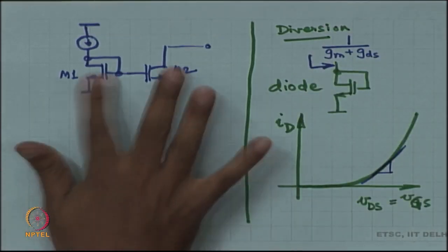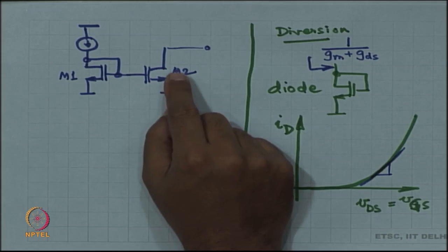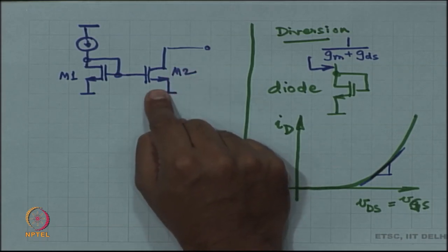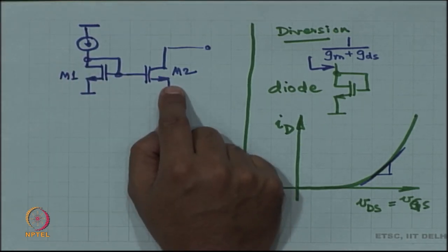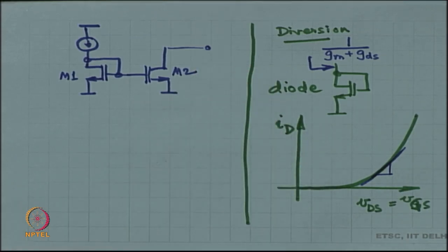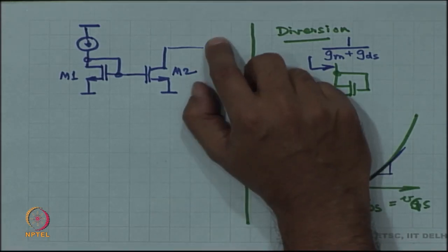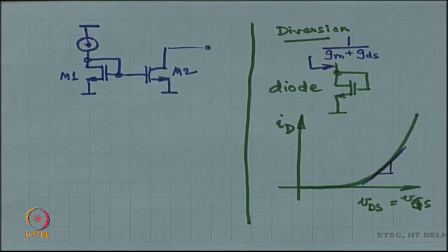All right. So, getting back to our current mirror circuit. So, we looked at two things. Number one, we looked at was value. The value is obtained from the reference. Number two, we looked at is the output impedance. The output impedance of this is nothing but RDS. Okay. Number 3 is, what is the set of voltages for which M2 remains in saturation and the device actually works like a current source.